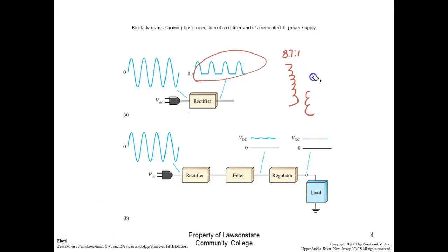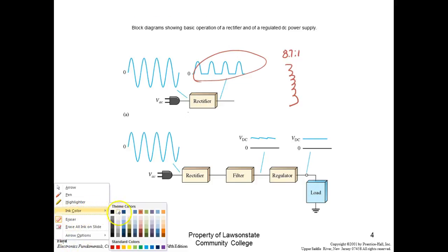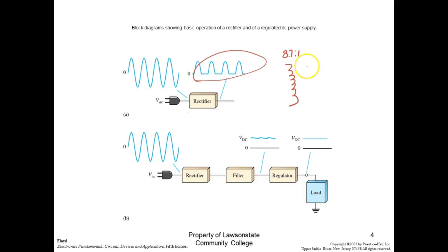When you run into transformers, you need to be able to figure the ratios, because a lot of times they don't show the primary with more turns than the secondary. Usually the symbols they show are going to be the same size, so you need to understand the ratios. So this is what we got. We got a center tap transformer. We're not using this lead. We have it disconnected. I have a diode pointing in this direction, and then I have a resistor.